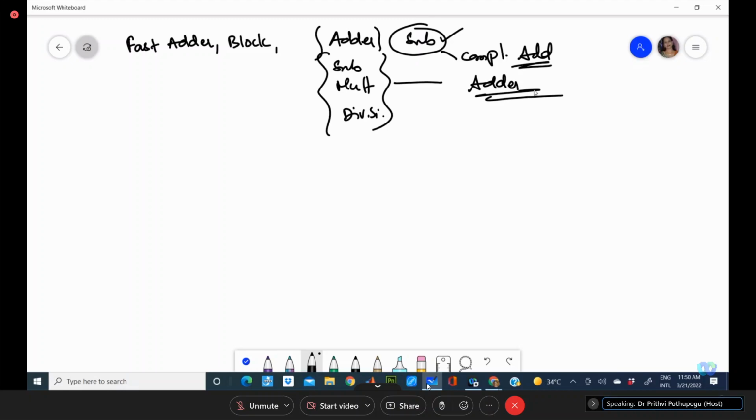If you can thoroughly understand what an adder is, you can play with the circuit now. You can change that into any sort of adder, subtractor, multiplier, or division. Normally, division is repeated subtraction, and repeated subtraction is nothing but repeated addition of the complement.